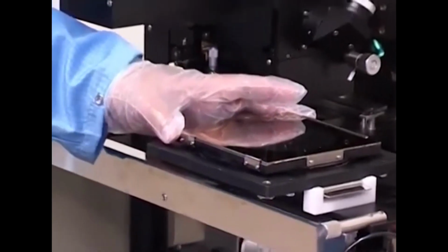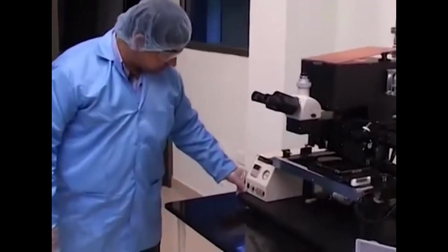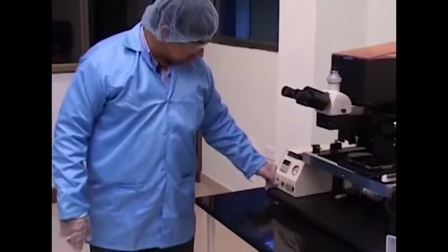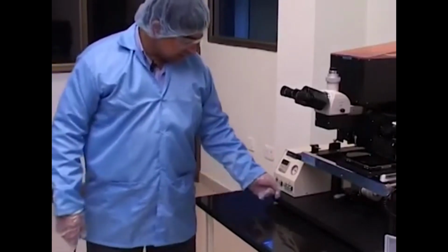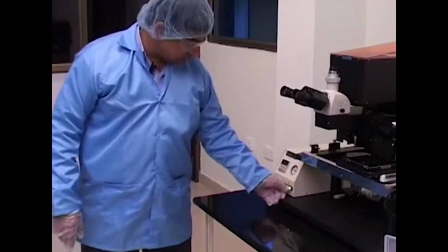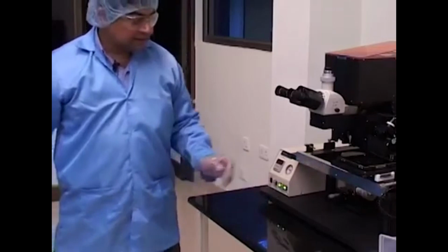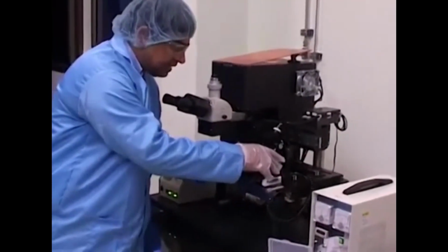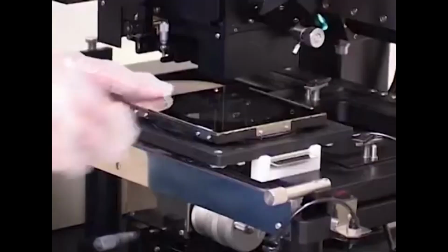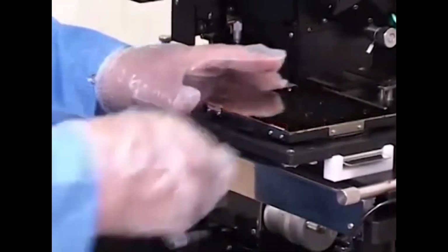We need to make it active by using vacuum, which can be operated using this controller. Turning on the controller power, we use the wafer holder and the mask for the vacuum to be operated onto the mask. Now if you see, the mask really is held very firmly. So now we have it mounted and well connected with the vacuum from the system.